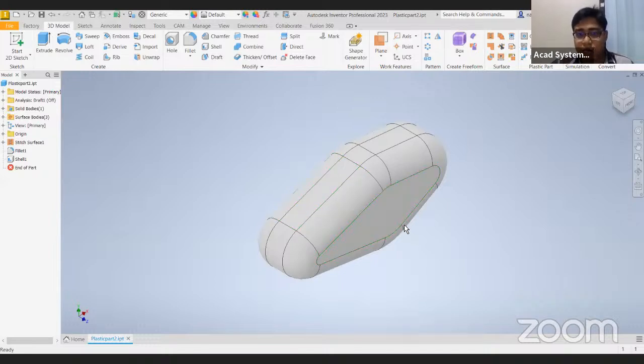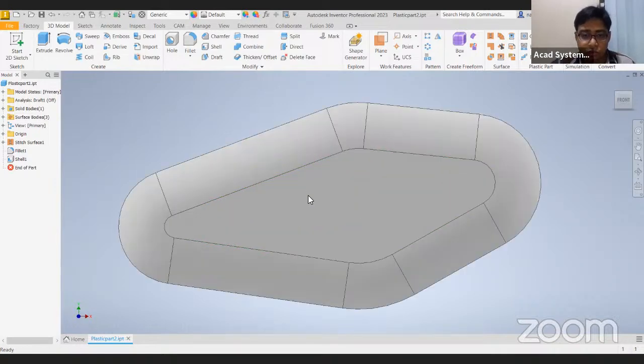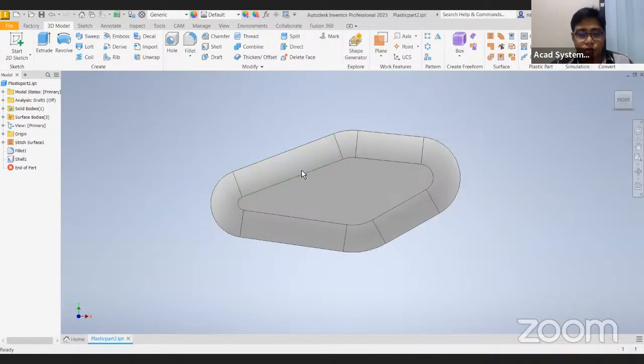And then lastly, once we have created these plastic parts, we're going to insert this into the mold base. So basically, we're going to generate a mold base. Inside of the mold base, you should have this core and cavity. So we're going to cut this into two, but we cannot just cut using straight cuts.